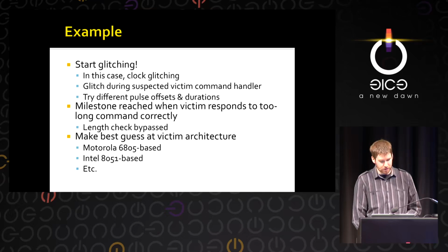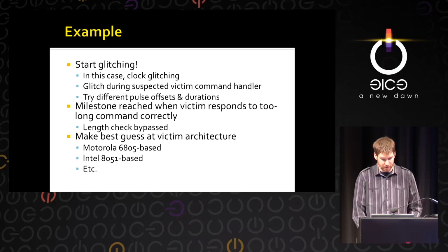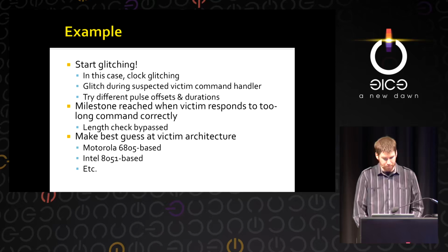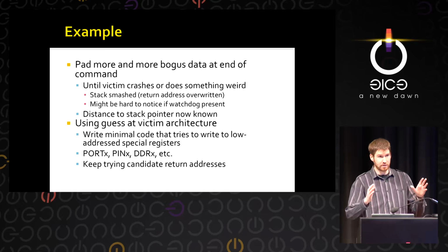At this point, there are usually Motorola 6805-based cores or Intel 8051 cores in the majority of smaller 8- or 16-bit embedded devices, so use that as your guess. As I said, you pad more and more data to the end of the command, and then wait till the victim crashes or does something weird.